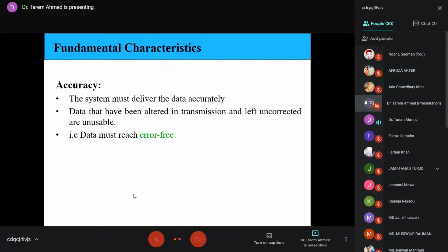So now let's get to a real world scenario. Suppose you have transmitted a 5-volt signal as a 1 and a 0-volt signal as a 0. What will happen in the transmission medium is that after a kilometer, noise will keep getting added to the 0-volt and the 5-volt signal, and some of it will also keep getting absorbed. So a 5-volt pulse may be received as a 4-volt pulse. A 0-volt may be received as a 0.5-volt pulse. Do you see that can happen?